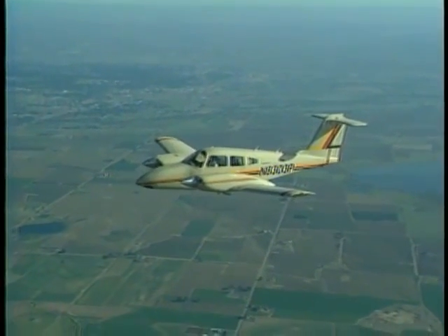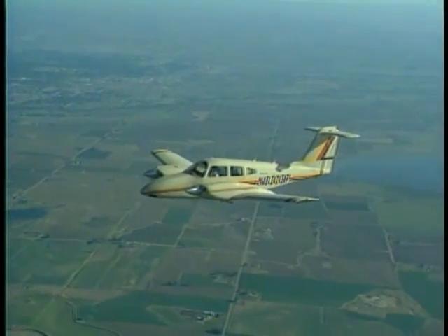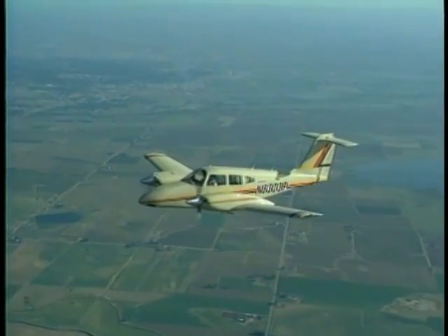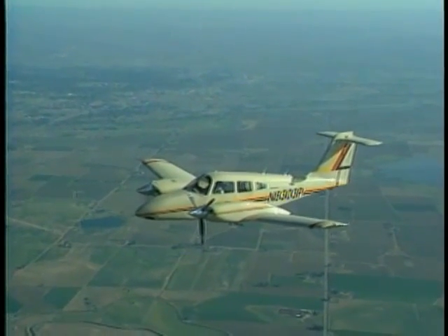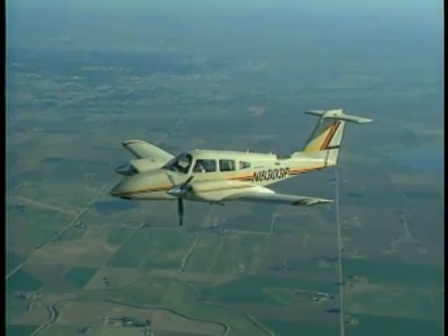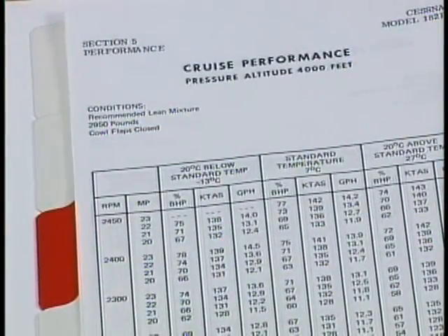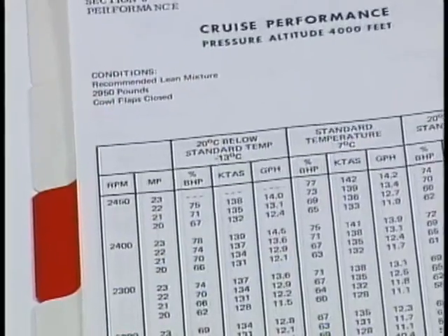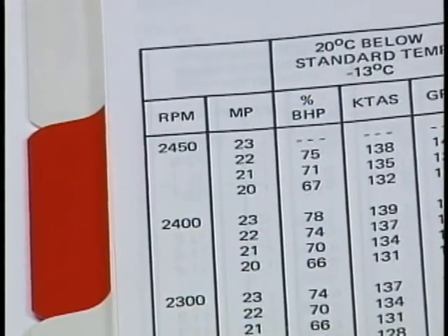In certain propeller designs, an addition of oil pressure directed to the propeller piston increases the blade angle and decreases RPM. A complete loss of oil pressure in the prop hub system causes the blades to move to low pitch, resulting in high RPM. This provides the benefit of having maximum power available as long as the engine is running. In other systems, the opposite is true, and a complete loss of oil pressure in the propeller hub will create a low RPM situation. This system is valuable in multi-engine airplanes and allows feathering of the propeller when an engine loss occurs. The pilot should also understand the relationship between manifold pressure and RPM and know how to determine proper power combinations.